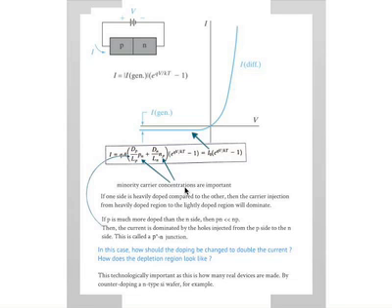And the reverse current, which is this part here, is determined by drift. And the drift is a minority carrier drift. It is the electrons on the p-type which, when they reach the depletion region, get swept across to the other side. That's a minority carrier drift. That's why that number is small. If one side is heavily doped compared to the other, then the carrier injection from the heavily doped region to the lightly doped region will dominate, which is obvious.